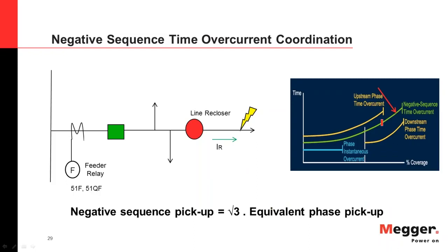So it's clearly visible now that my negative sequence curve is more sensitive towards line-to-line faults. As I said, it's only happening in case of line-to-line faults, and it's more sensitive towards them. So I can use this element just to have more sensitivity.